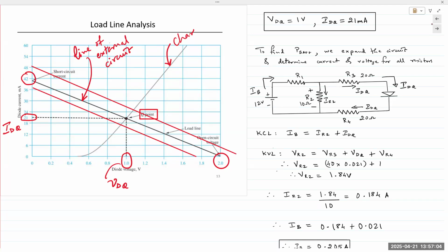Obviously, if you're applying Vs equal to 20, well, you'd have to calculate, sorry, you'd have to calculate the Thevenin voltage. Again, you have all the equations, so you'd be able to calculate the voltage. Anyway, the point being, you change the supply voltage to 5 volts, to 10 volts, to 15 volts, and to 20 volts. Your Thevenin voltage would change. Simply plug in the numbers, calculate those, and then find those 2 points right there, the voltages and the currents. So in response to the external supply, that Q point is going to shift either up or down the diode characteristic.